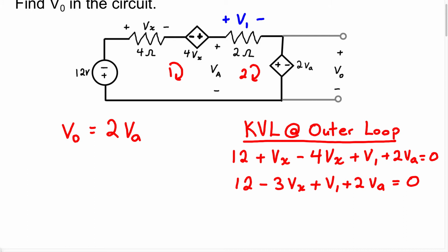So for example, we know Ohm's law states voltage equals current times resistance. So when we look at this, we know to find the voltage in each resistor, we're going to need a current. Do we have a current label? No, we don't. So once again, we're just going to have to add in a current because we know a current is going to have to be flowing through this circuit. So once again, we have to use the basic knowledge of circuits that we know to solve this problem. We know there's going to be a current. Now you can choose the direction of the current. I'm going to draw the current in a clockwise direction. So I'm going to say the current is going to go this way.